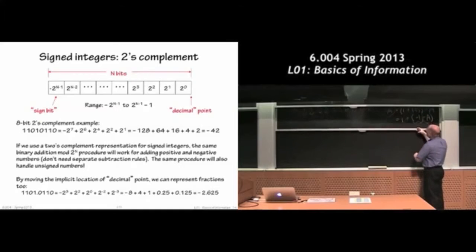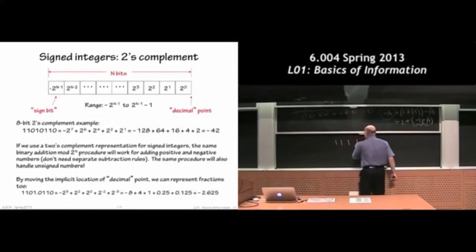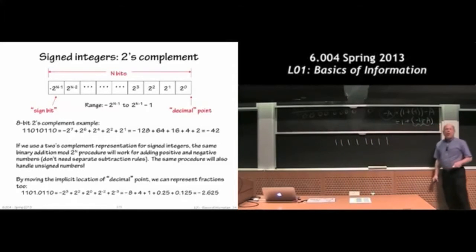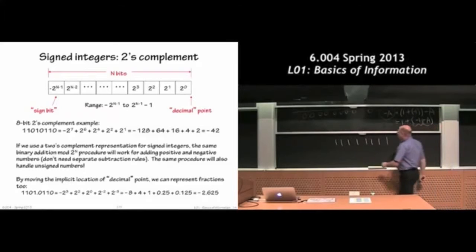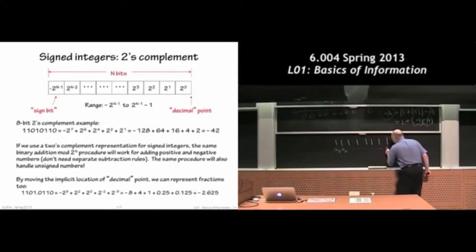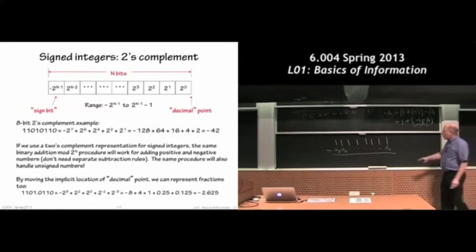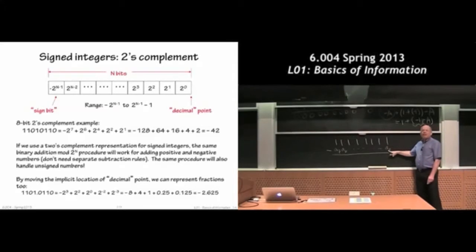Okay, so keeping that in mind, I'm going to slide that up just a little bit. What was minus 1? It was all 1s. And I'm going to subtract from that a. So I have a, these are the individual bits of a, all the way down to a0. I'm going to subtract that, and here I'm just going to use regular binary subtraction, although I won't have to do that in my hardware. What is 1 minus a bit? Suppose a0 was a 0, what would be 1 minus 0? A 1. If a0 was a 1, what would it be? 1 minus 1 would be 0.